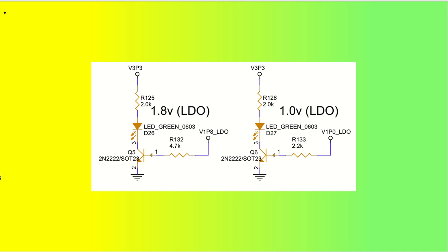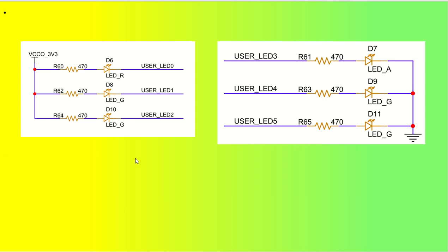Let us say some more circuits are there. We have 1.8 volt, 1.1 volt. All these indicators are utilized in our FPGA circuits, so we need to understand how to make use of our simulator to do the job. Similar to that, we can have another kind of LEDs. Let us say this is going to get connected to my microcontroller or FPGA IOs. Whenever my FPGA IO is low, this will start glowing.